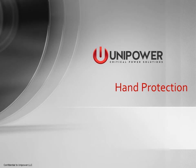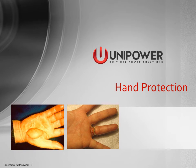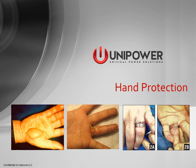Hand protection. Hand protection is very important to our operation. Most of our employees work with their hands, building or testing equipment. Below you will see pictures of folks that did not have proper electrical hand protection and the type of injuries that they had. One particular injury is the ring finger. As you will see in the last two pictures, these are pictures of burns that occurred while folks had their wedding rings on during testing.